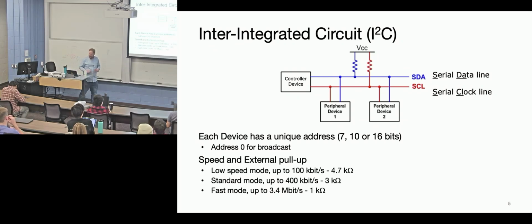One of the challenges, as we'll see, is that speed is now not defined just by silicon. If you want to go faster, well, those resistors are going to control how fast that line gets pulled back up. If it's a very large resistor, meaning that it weakly pulls up current, well, it can't pull that line up very fast, and so you actually get slower data lines. And if you want to go real fast, you're going to have a smaller resistor.